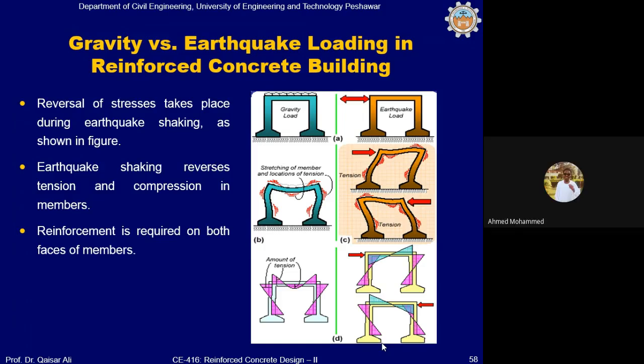Okay, and now what is your question? How to reduce that? Okay, how can you reduce this? You can reduce this if you prepare good concrete which has less moisture, which is called high performance concrete, by reducing the water-cement ratio and adding some plasticizer in order to achieve good strength. When pores are fewer, basically these are the pores in concrete which are compressed with time under sustained loading.